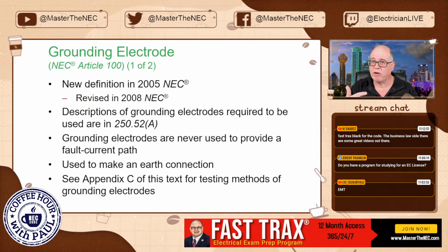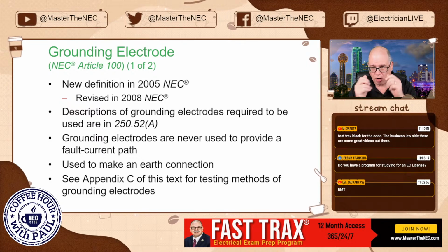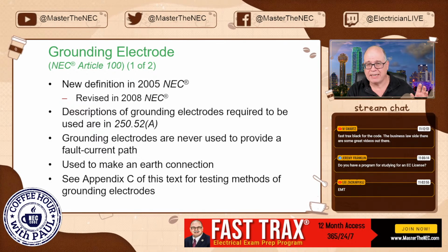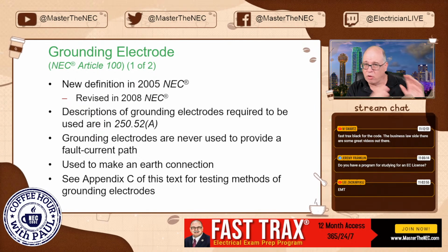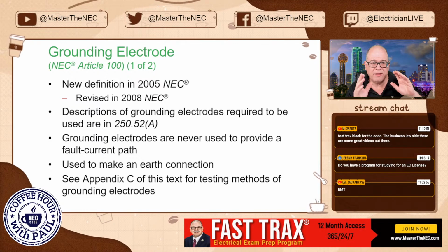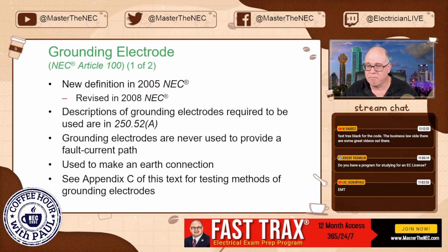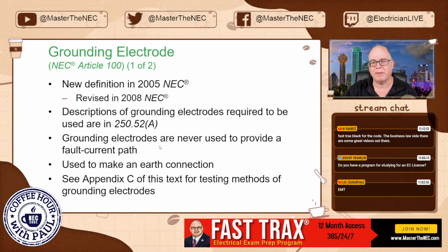So all we're trying to do is establish connection, and it also stabilizes the voltage in all of our testing throughout the electrical system. That's all we're doing with it. Lightning, surges, high power lines to low power lines, all those types of things, voltage stabilization, that's the purpose. Not for clearing any devices. Remember that concept and make sure you convey that to your apprentices and everybody else.